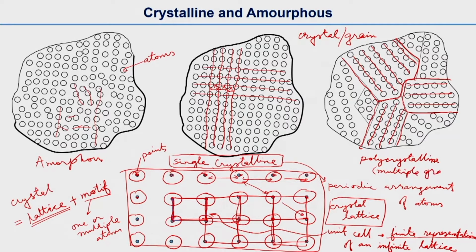And as you know, most metallic materials are polycrystalline, because these grains are on the order of micrometers, like 10 to 100 micrometers, but sometimes you can make very big grains, like single crystal turbine blades. Engineers are now so expert they can make even very big grains in centimeters or meters, and also very small grains at the nanometer level. The range of grains, that is called nanocrystalline material, from nanometer to probably meter, you can make depending on your expertise in metallurgy and materials engineering.